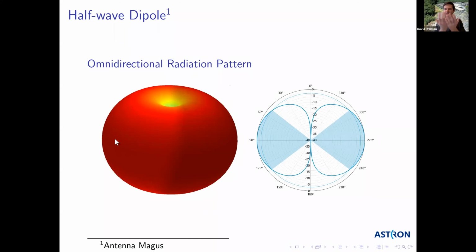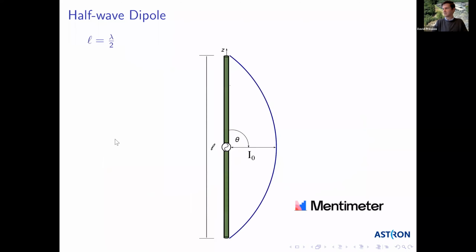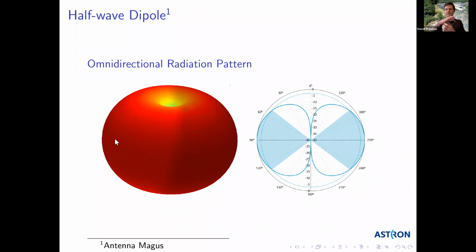So you've got a surface current distribution that is shown in this graph, not just along one line. And it's maximum power radiated all along around theta equals 90 or 270 degrees. And if you were to take a cross-sectional cut in the H-plane, so the H-plane would be dissecting the dipole here, then you've got an almost perfect circular ring for the radiation pattern.